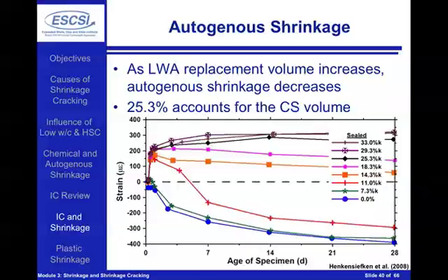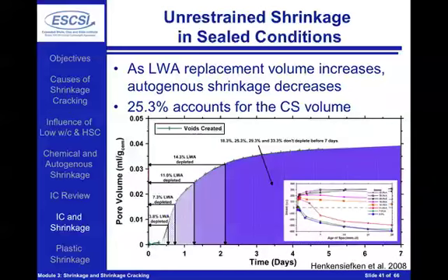And if we add in additional internal curing water, we're not going to see any additional improvements after that particular time. The takeaway, though: plain concrete has autogenous shrinkage, no drying taking place, but just shrinkage because of these vapor-filled spaces that are forming due to chemical shrinkage, resulting in self-desiccation. Adding internal curing water has benefits. If we make sure that we add the right amount of internal curing water, we'll see a slight expansion and then essentially no shrinkage as long as the concrete stays sealed.